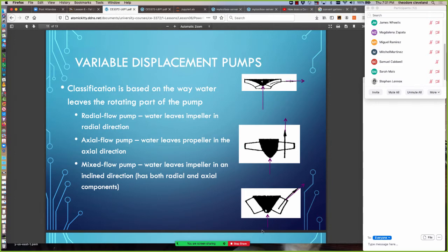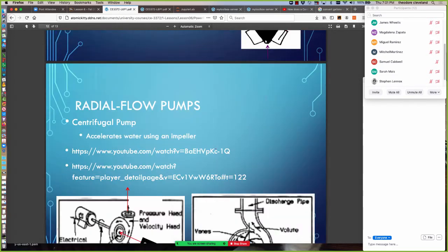But these are desirable for submersible use, like down a well bore, because they don't have to have very big diameter. I mean, we're not talking teeny diameters. They're 4 or 5 inches in diameter, whereas a propeller pump is several feet in diameter, and a centrifugal pump is at least 6 to 8 inches in diameter at the impeller, and with a housing it gets greater diameter still. And so that's the main difference mechanically.